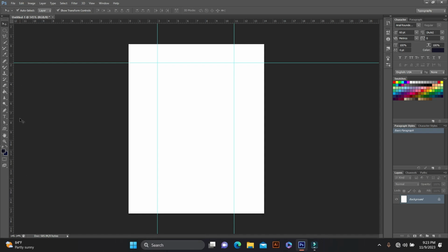To do that, this top left corner, this origin in here, you can drag this origin down to here and drop it like that. Now you can see the centimeters from the bottom also start at 0. Now you can drag one more guideline from here and drop it from the bottom into this area like that. Now if you want to reset, you can double click in this corner, and it will go back to the same position.